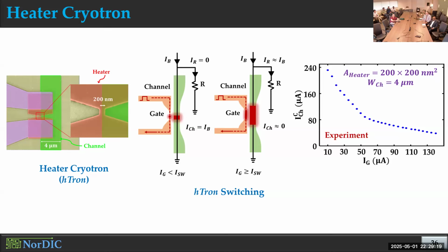But the SQUID, is that the same physics-based model you showed there, or did you have a more compact model? The ferroelectric SQUID model, we use those physics to develop a compact model. Because you see the equations are actually compact and we could implement them in Verilog. So we developed a Verilog-based compact model for the ferroelectric SQUID device using those physics.